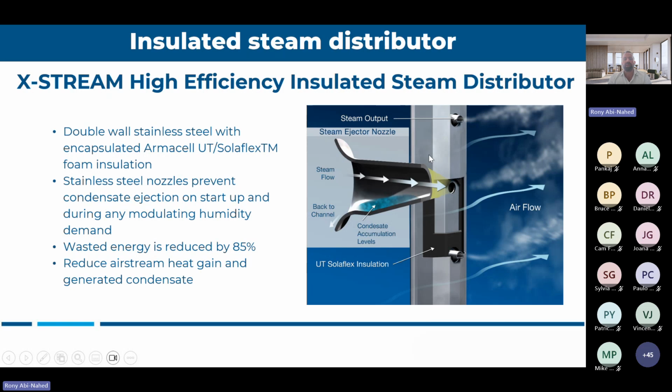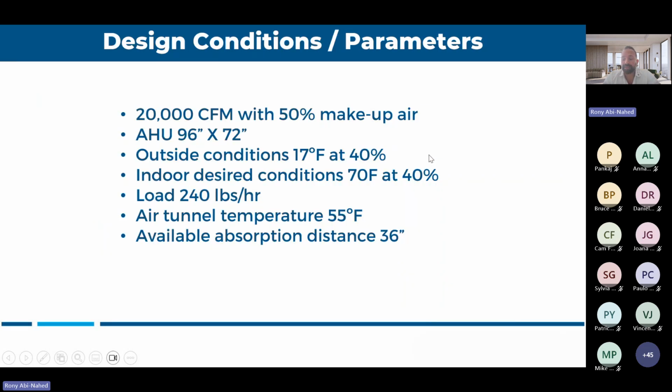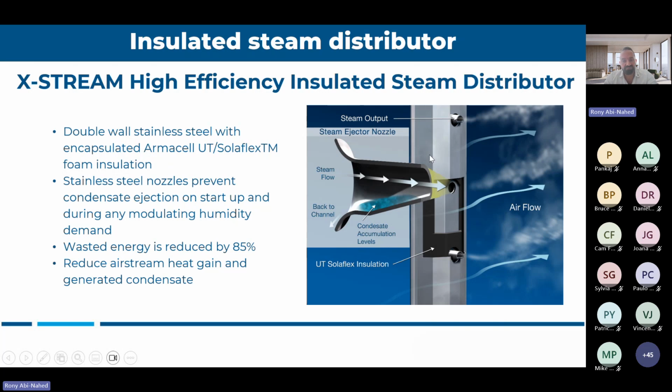Each manufacturer has its own way to insulate. You can have a PVDF insulation, and then you encapsulate that with stainless steel. So you can go up to 85% efficiency on insulation, which is huge. Some others will just have PVDF without stainless steel. Some others will have double wall stainless steel without the PVDF. So it really depends. But to be honest, based on my experience, if I can recommend something, always try to specify a company that has a double wall stainless steel insulation.